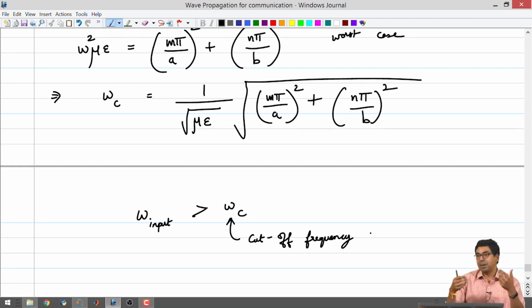Because we had all this prior knowledge, we had a different way of getting a valid solution. But even though we did that, for the case of parallel plate waveguide, we still did it with the original method, where we write the incident wave and reflected wave, write down the expressions for the incident and the reflected, and take the sum of the two to form the total field. So, these are two approaches to find the expressions for the electric fields and also to find the cutoff frequencies.